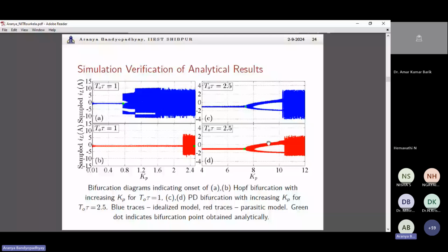That is why there are two lines. And in this case, the stability is lost to Hopf bifurcation. Note that you can predict this type of instability through Bode plot or any linear type of analysis. But for predicting this type of instability, you need some type of discrete time approach or Filippov method, or the other method.